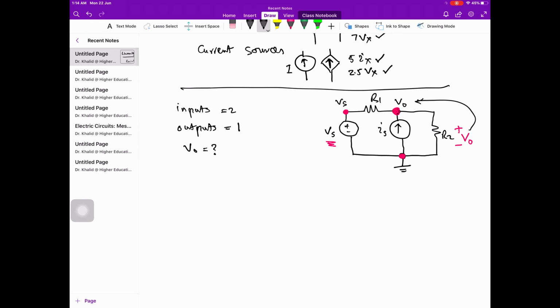So this is VO, with current flowing away from the node due to our assumptions, as discussed in the node voltage method. VO minus Vs divided by R1, plus the current through R2 flowing away from VO, VO minus 0 divided by R2, and the current we stick to the direction of the current source, so this current is coming towards the node.